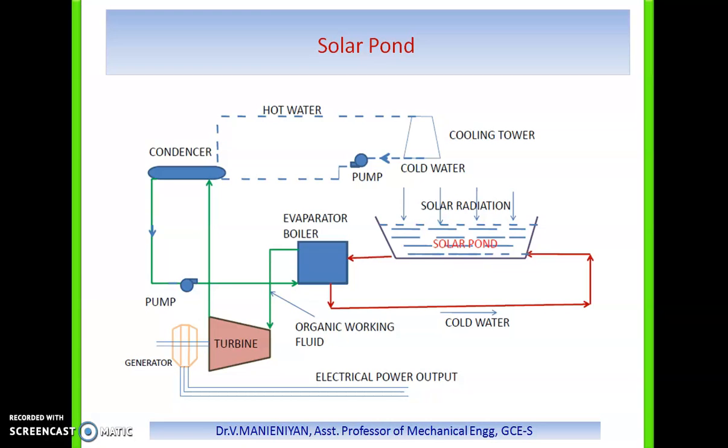It is not practical to cover the bottom of the pond with an array of pipes acting as a heat exchanger, for this reason: the cost will increase, and the heat transfer from the hot brine around a pipe by convection will be very poor.